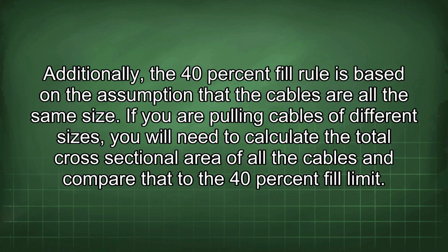Additionally, the 40% fill rule is based on the assumption that the cables are all the same size. If you are pulling cables of different sizes, you will need to calculate the total cross-sectional area of all the cables and compare that to the 40% fill limit.